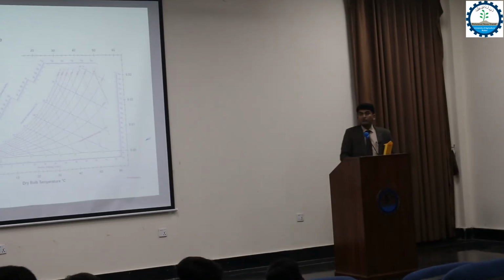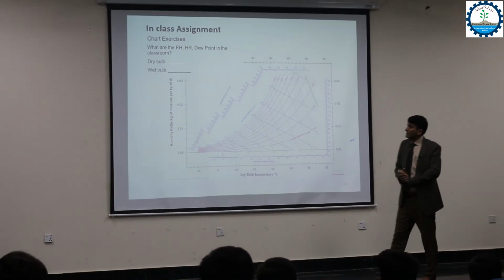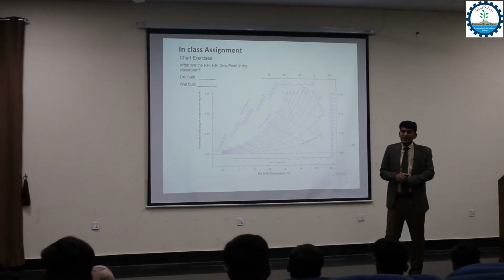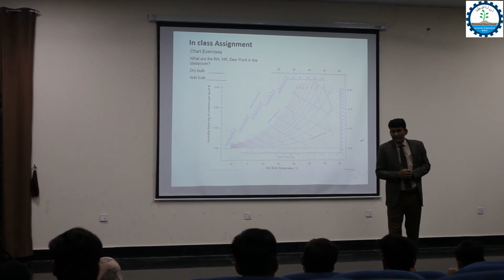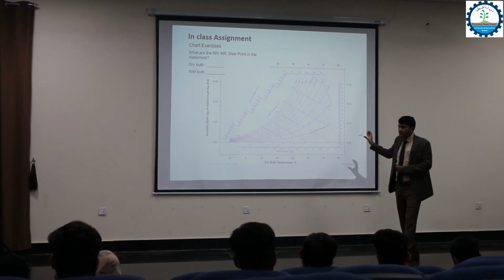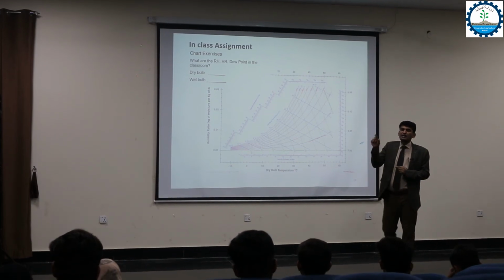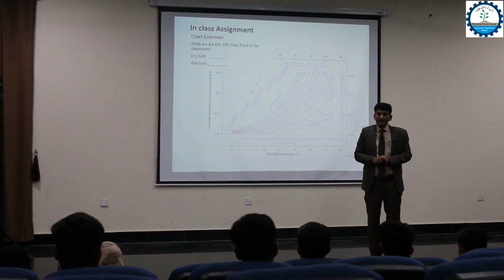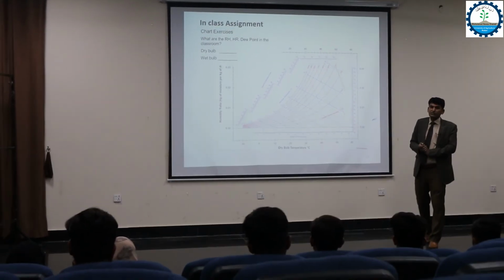So use dry bulb 30 and wet bulb 27. Predict the other values; you already have a printed psychrometric graph in your hands. Sketch all the other parameters, draw their lines, and encircle the specific values on the psychrometric chart, and you will submit your CR after 2 minutes. Okay, please continue.